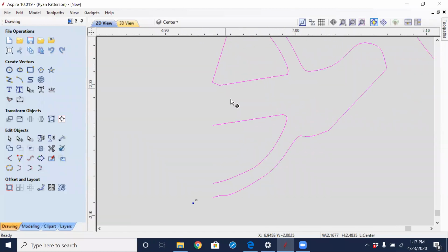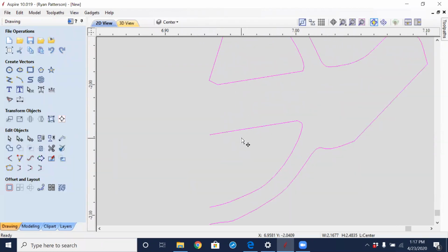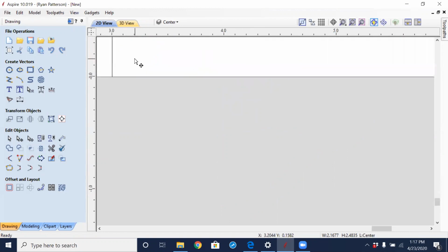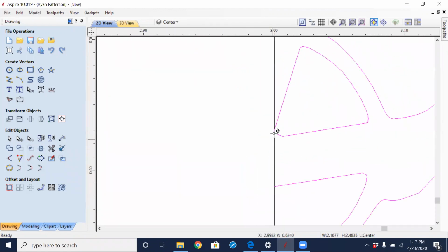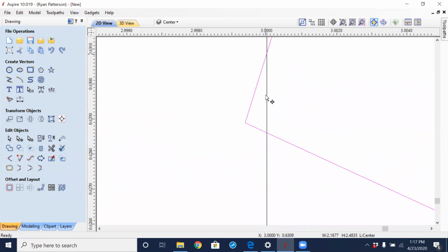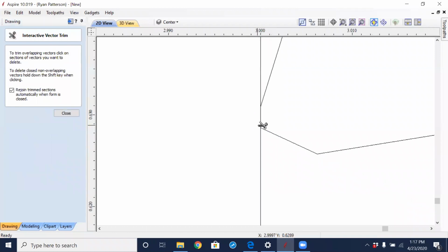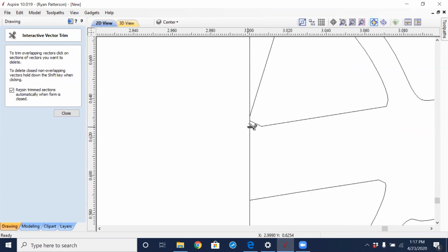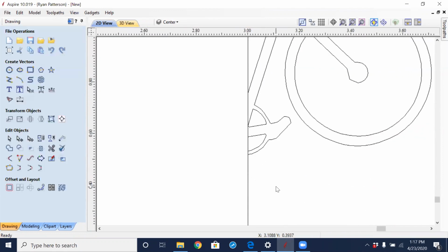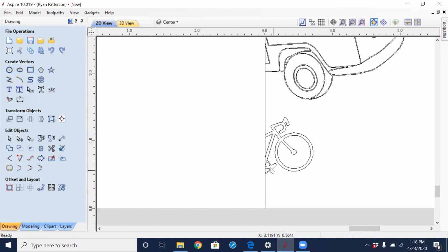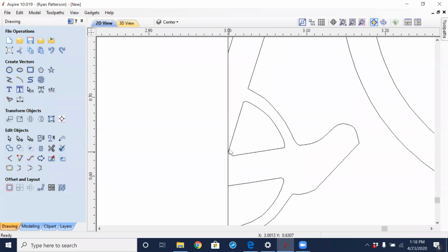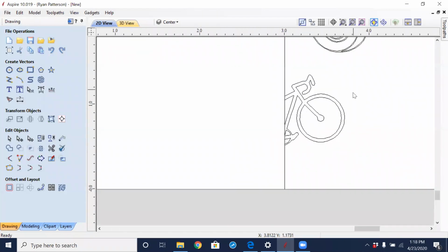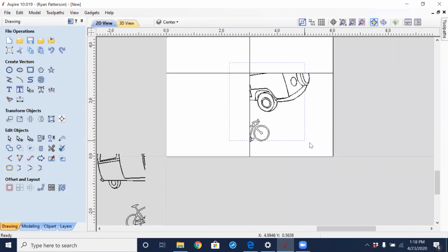Now there's one little bit that caused us some issues there. I'm going to undo to put that back up to see if I caught that area that I didn't. So I'm going to ungroup that. I needed to trim this away off of the left side there, knowing that I don't have that line on the other parts. I want to create that. So we've got to remember there's a little bit of a missing gap there, because in the end we'll end up with an open vector that's not going to be good for us.